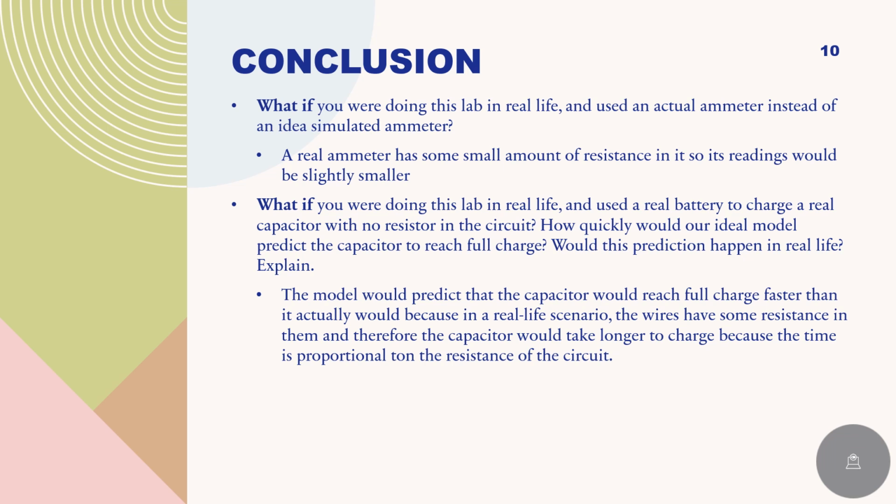So some concluding questions. What if you were doing this lab in real life and used an actual ammeter instead of an ideal simulated ammeter? A real ammeter has some small amount of resistance in it, so its readings would be slightly smaller.